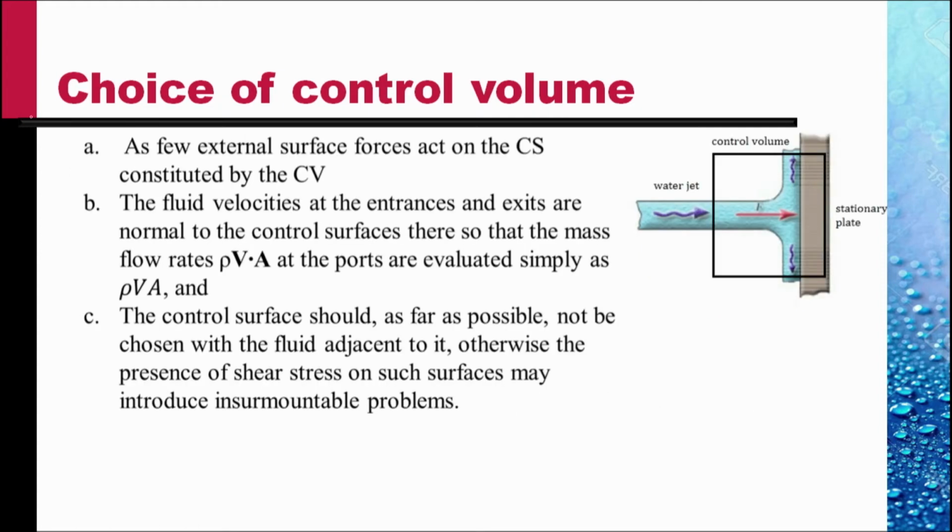Now, we have to choose the control volume. The choice of the control volume is dictated by the following suggestions. A, we should choose a control volume such that as few external surface forces act on the control surface constituted by the control volume. Obviously, the fewer the forces, the fewer terms we will need to incorporate within the equation.